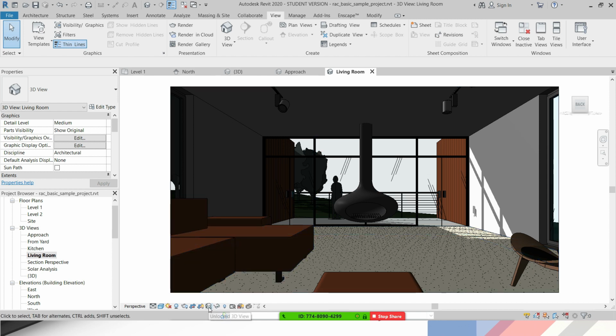If it's locked, okay. You will see this small button with the lock, the 3D with the lock button. Just click it and make sure that it's unlocked. It's at the bottom. The 3D unlock button is coming in the properties palette. No, it should be at the bottom panel, the view control panel, under the drawing area. We'll come back to that. If you need specific assistance with this, you can share your screen with me after the session.